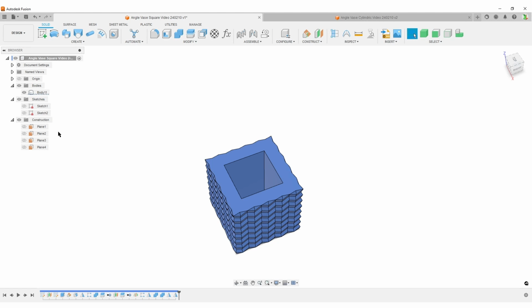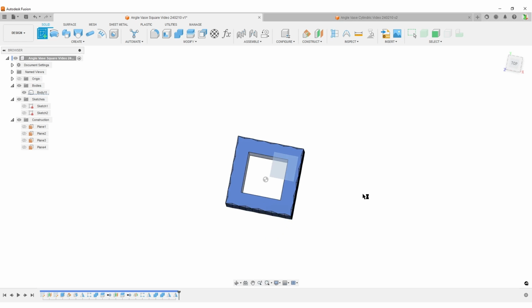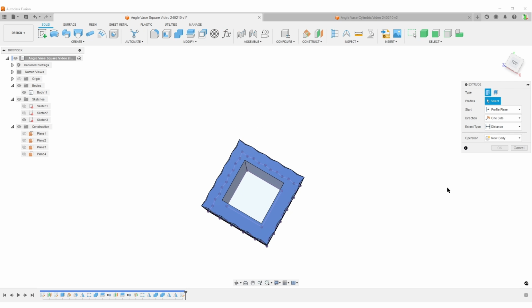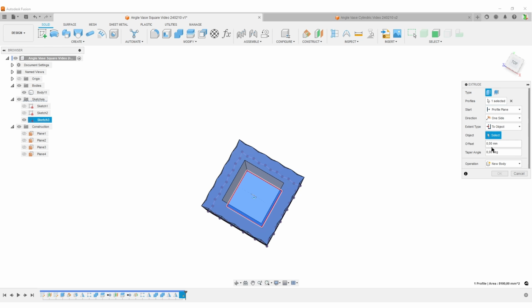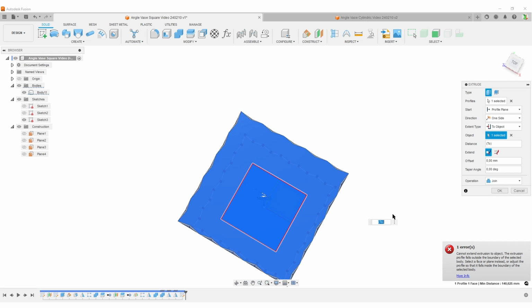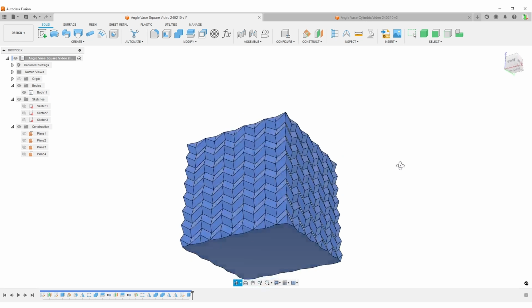So what we can simply do is create a sketch at the bottom plane. We will project in the face up here. Hit OK, finish sketch, E for extrude. Only select the center rectangle, distance to object, up to the top. Oh, sorry, not that one. Up to the top, like that. I'm going to hit OK after join, and we are given one single full body.